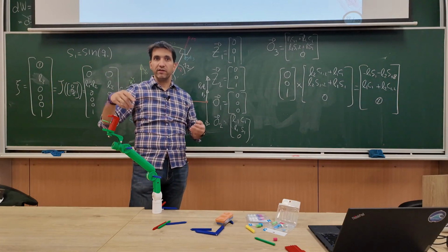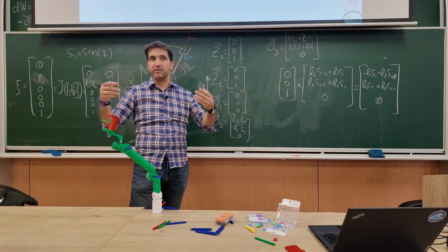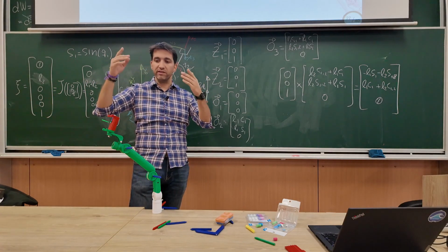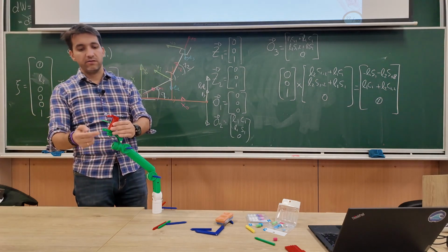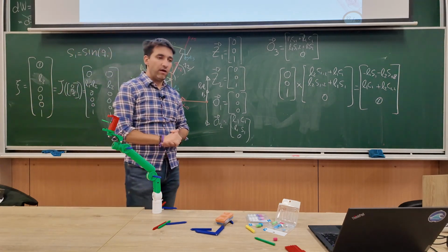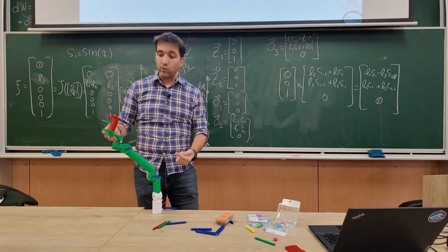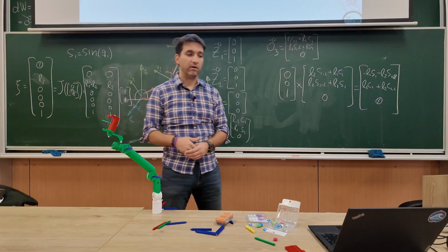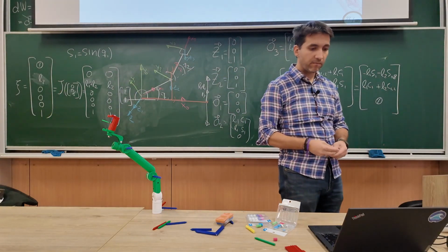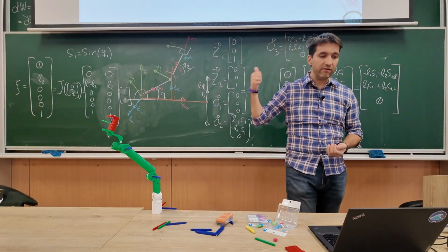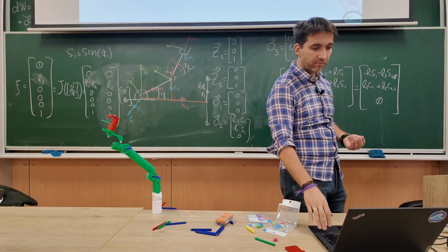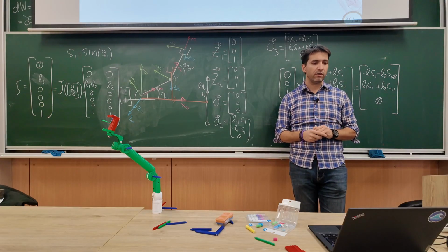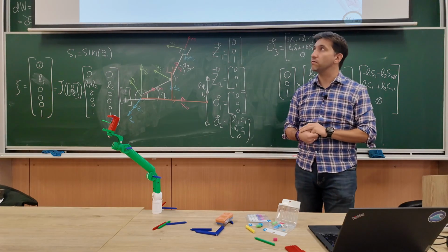The end effector velocity is my reference, is what I want as an output, and I can say, okay, I want this velocity, say moving around the z or the y or the x, and I want to calculate what would be the necessary joint velocities for this end effector velocity. So basically, I want to calculate the inverse of this. Could I do it? And if yes, how could I do it?